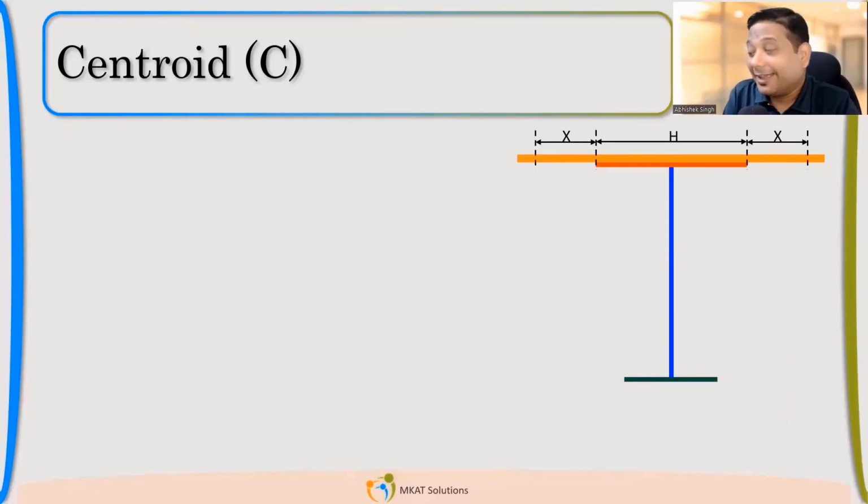See, we are manufacturers, so any design is done considering the manufacturer's perspective, right? So any advantage there is, definitely we will take. If the splitting force is trying to split even your cross section of shell, the top part will also participate in preventing it, isn't it? Do you agree with me? That this shell portion, now what length will be participating, that is a different thing. We'll talk about that.